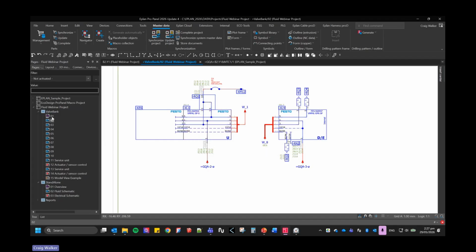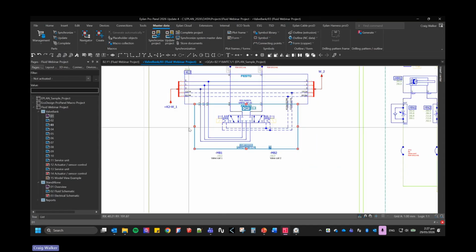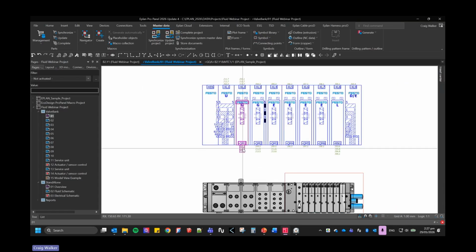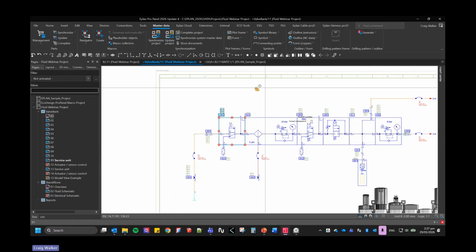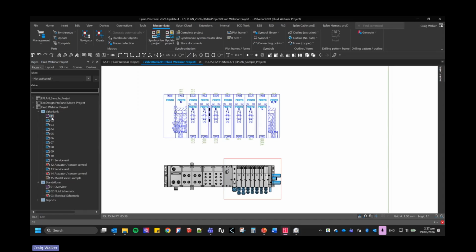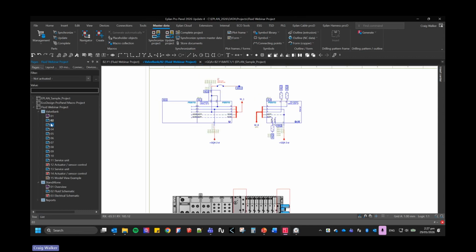So if I was to jump back to the overview, I can choose one of these valves. I can see the pages it's represented on, and then it will take me exactly to that valve. And I can jump back as well. And it has other representations as well in terms of more detailed breakouts here. And this is the back-end supply for it, as well as the mufflers. So that's the layout for your pages, or how to start laying out fluid devices in your project, obviously with overviews, individual valve breakouts on different pages.